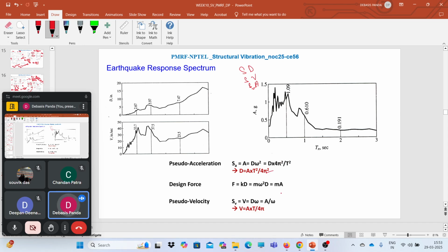So here we have all the information. For a corresponding earthquake, the input will be given, the damping ratio of the structure should be there, and omega n we have. So we can easily calculate the maximum values and use them to calculate the responses of different stories.